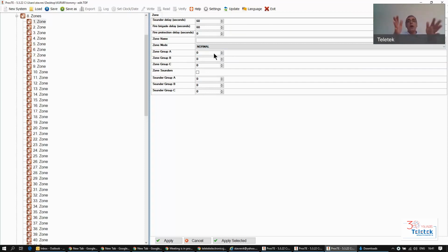Imagine you have a hallway with 3 stores, and the hallway needs to be a common zone for the 3 different groups, for the 3 different stores. If you design an input that monitors a group for fire, the zone that belongs to the group will trigger fire in this group as well. So it's a common zone between the 3 stores.